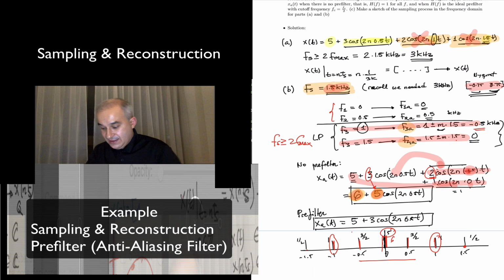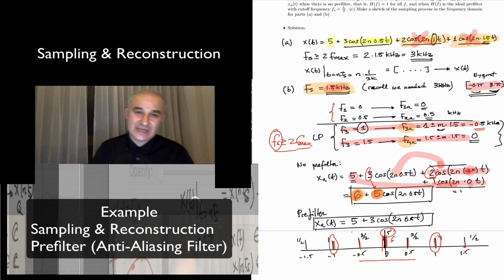If you meet this, you can reconstruct the signal perfectly. If you are constrained by your sampling frequency, you still need to band limit, because otherwise you corrupt even the section of your signal that could have gone through.